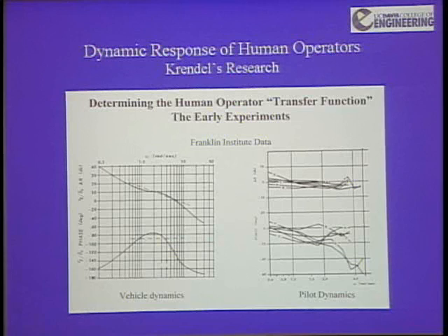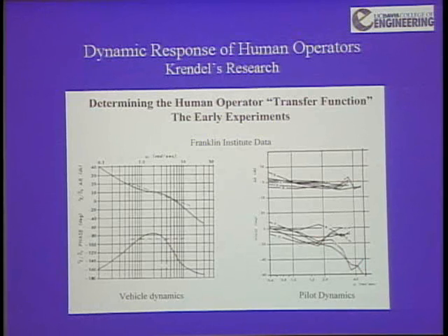Well, the human operator has an inherent time delay. 300 milliseconds is about what you'll see, and the effect that has on a Bode diagram is a constant phase roll-off. What's going on back here at low frequencies is the human is creating a type 2 system. Low frequency integration to zero out steady state errors.